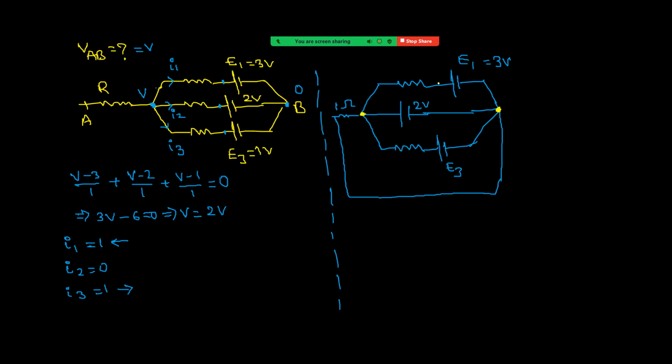So this is now discharging and this has to be charging. The potential difference V equals epsilon minus IR. In this, the potential difference is now 2, so 2 equals 3 minus IR. This is I1 into R, which is 1. Or take it as I1 dash to avoid confusion, since here we have taken I1, I2, I3. I am taking here I1 dash.